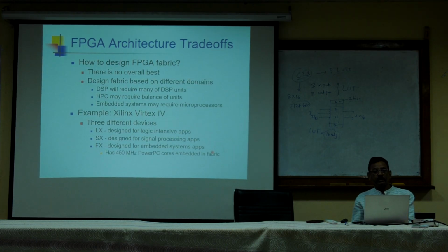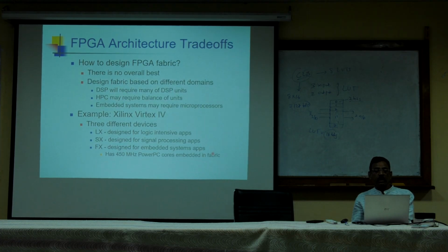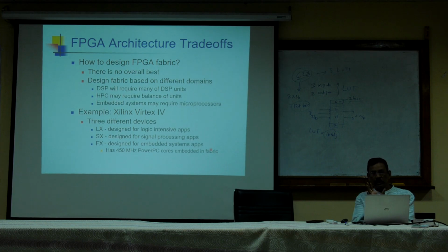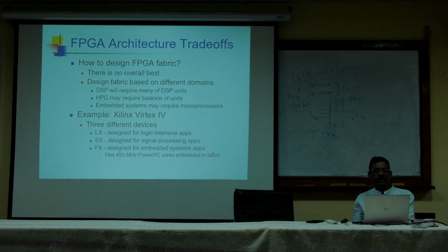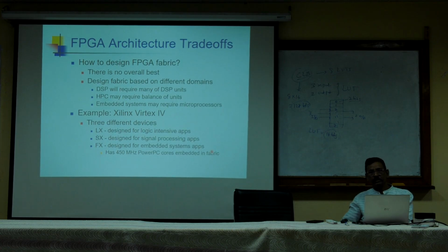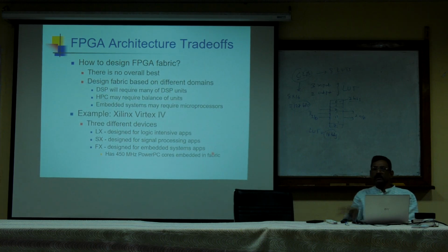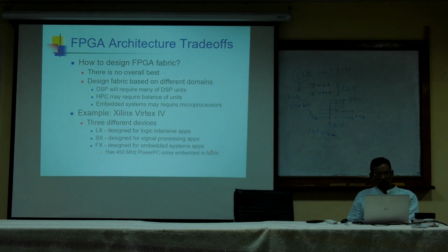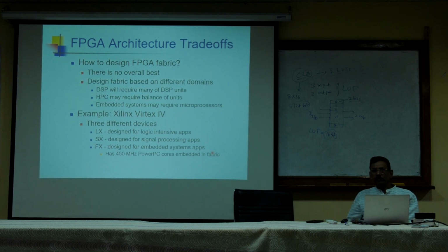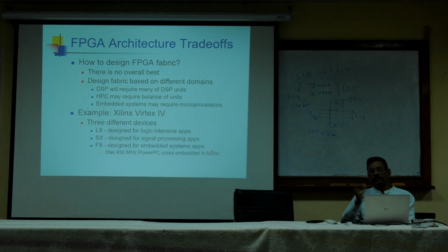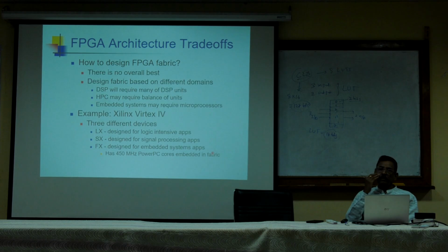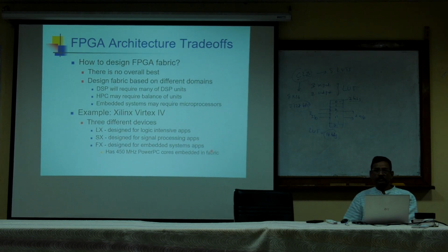How to design FPGA fabric? There is no overall best. Design the fabric based on different domains. One is DSP type of applications, second is high performance computing applications, parallel processing, high speed operations, and third is embedded computing, embedded system type.